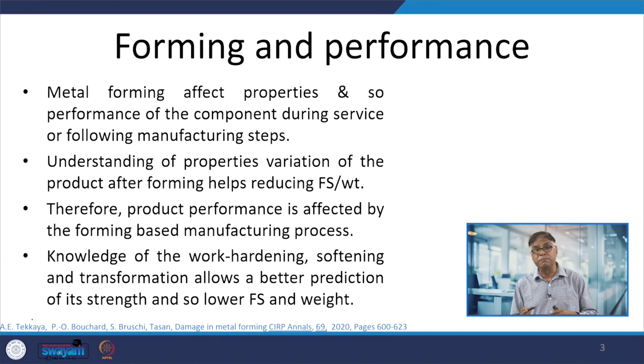So, that is why it is important to understand the way by which forming is going to affect the structure, properties and so the performance of the product during service. If you have a better idea of work hardening, the softening if any taking place, or the phase transformations which are occurring during the deformation, which in turn will be affecting the mechanical properties, especially the yield strength, hardness, ductile to brittle transition temperature and many other characteristics.